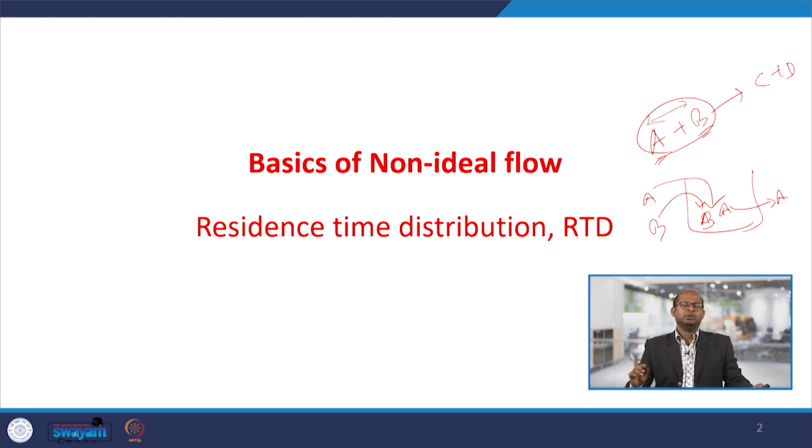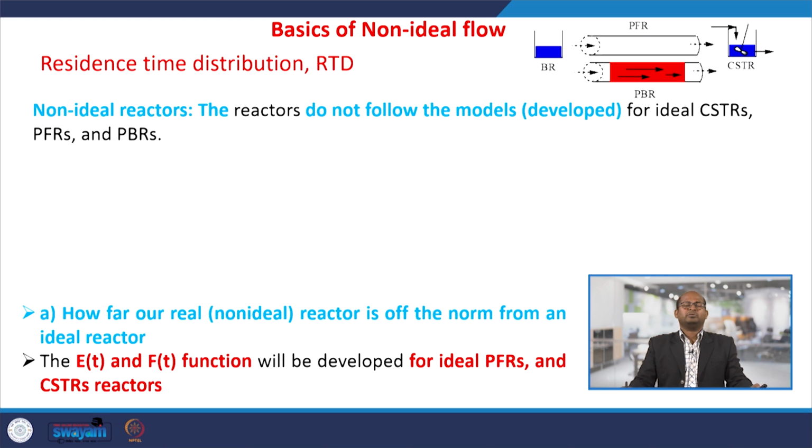So some anomaly is there once the reactants enter. Sometimes we get low conversions, sometimes high conversions, meaning there is fluctuation. That is due to the residence time distribution, the time they spend inside the reactor. Reactant to reactant it may differ, and that may be due to a fault of the reactor we have designed.